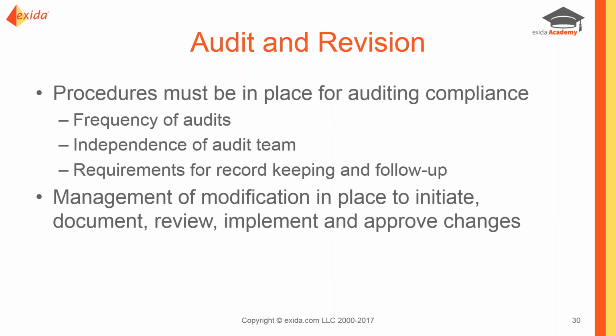Other than assessment, we may want to do some audit and revision requirements. So we do need to look into our functional safety management plan and have some provisions for doing auditing. When we get into the operating life cycle, the proof test activity is something that will be repeated over and over again for a long period of time. So we might want to do an audit on our proof test procedures, how we're doing our proof tests, how we're documenting them, and make sure that that routine activity stays robust throughout the life of the process, and that we are indeed identifying failures and correcting them in the way that we should.